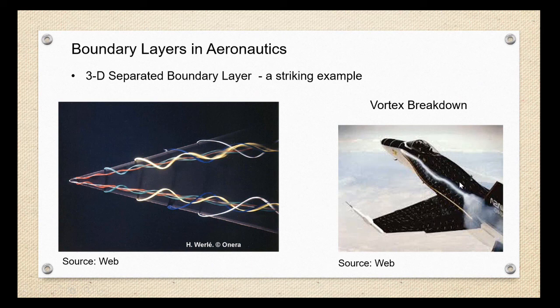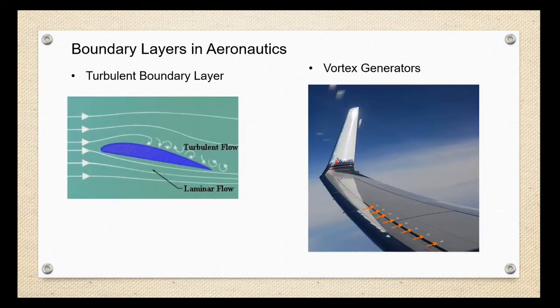And this is one visualization where you don't have a conventional delta, but you have a strake with a rectangular wing, and you can see a phenomenon called vortex breakdown, that of course has its own consequences for the stability of the aircraft.